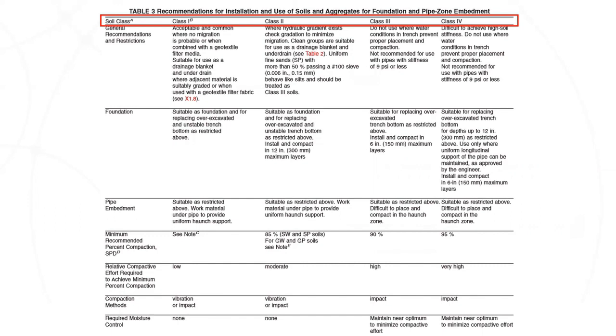Keep in mind, class 1 is that super soil, that structural soil you have to order specifically. Nobody has that on file; it's not a typical AASHTO specified soil, so you have to order it based on the design of that soil itself. So we focus more on class 2, class 3, and class 4 soils, because those are more readily available from your material provider.